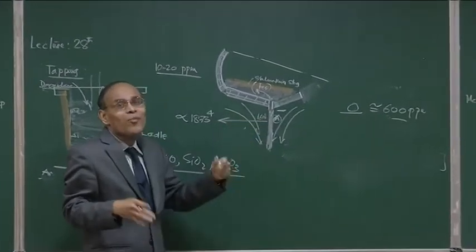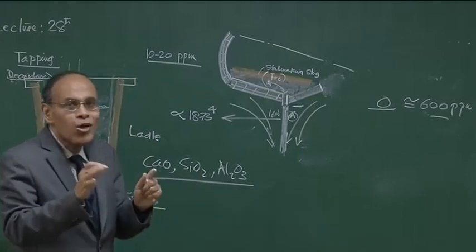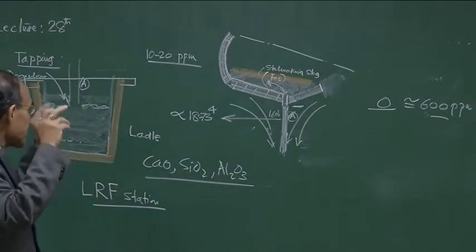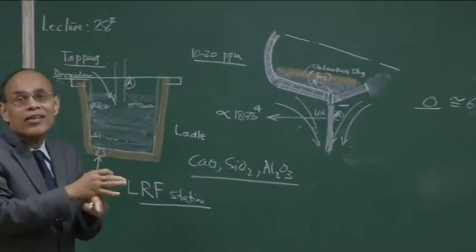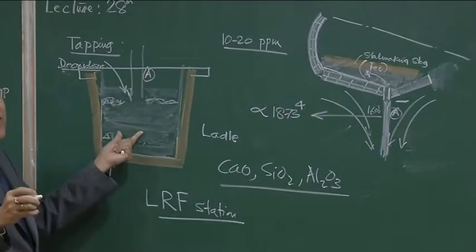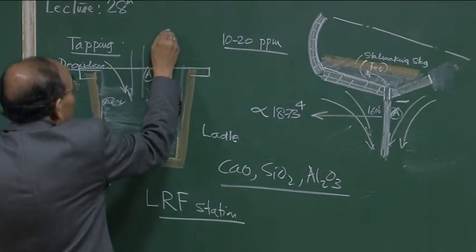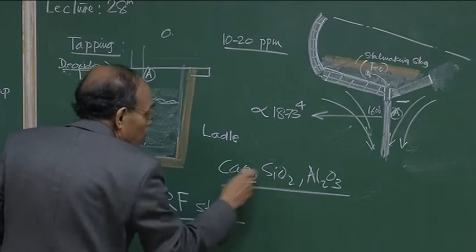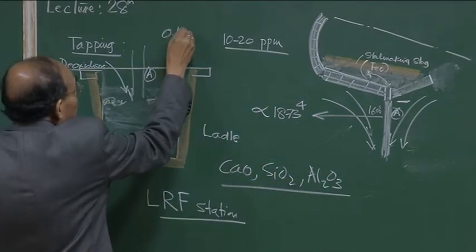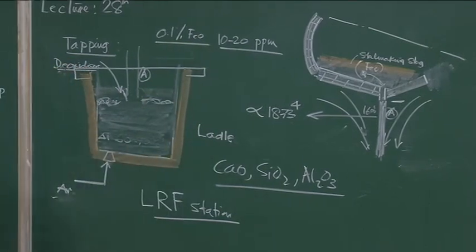Or there are electromagnetic and thermal imaging techniques also available, which allow us to cut off the moment we know that slag is coming in. We raise the converter, and then not a single drop of additional metal or slag can come into the system. In this way, it is possible for us today to ensure that the slag thus formed with the addition of the new species contains less than 0.1% FeO, virtually cutting off the slag itself.